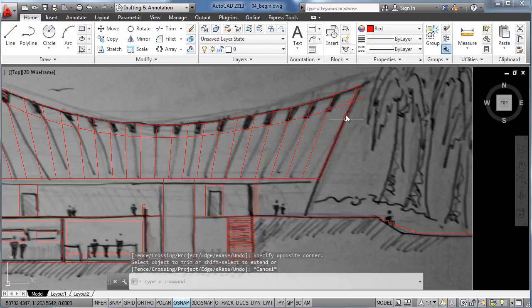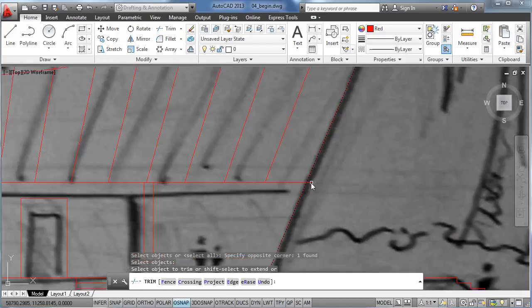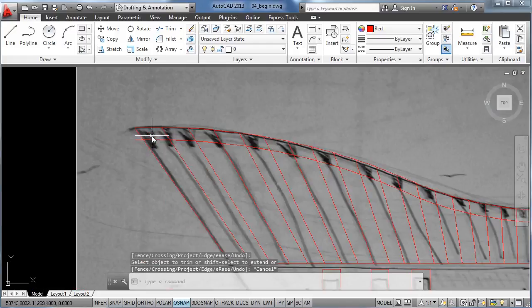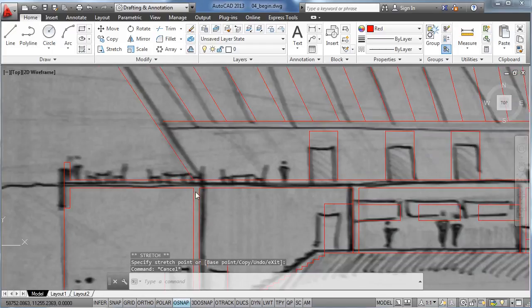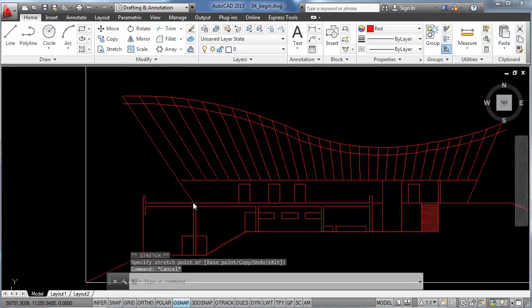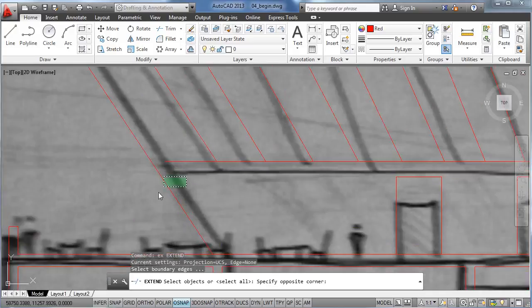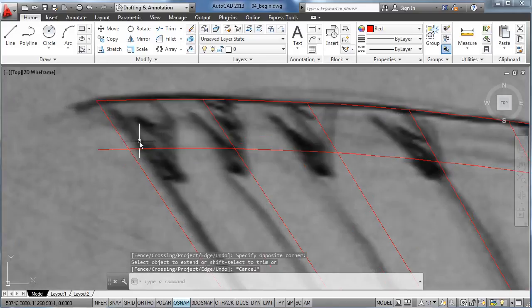And now we're going to make a couple of adjustments on our drawing. Okay. Also, we're going to move this line down here so the facade line goes at the same point of this wall, because it's going to be a bearing wall. Then we are going to extend this line using the extend tool and trim these other lines.